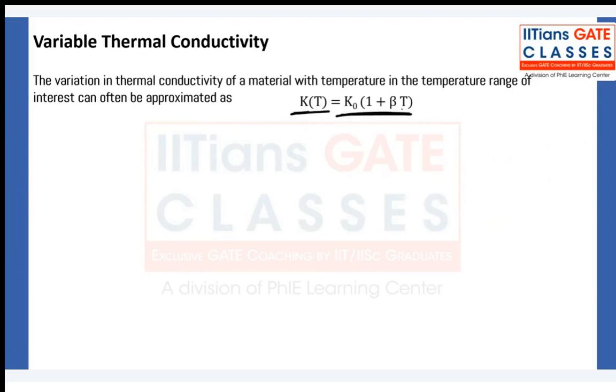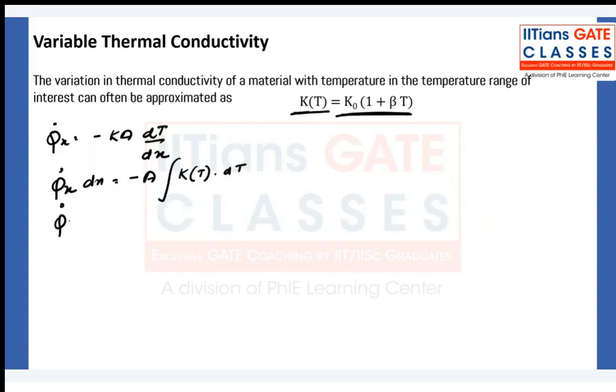Now you cannot take the conductivity outside the integration. Now what do I need? dx is equal to minus A integration K(T) dT, from x1 to x2.